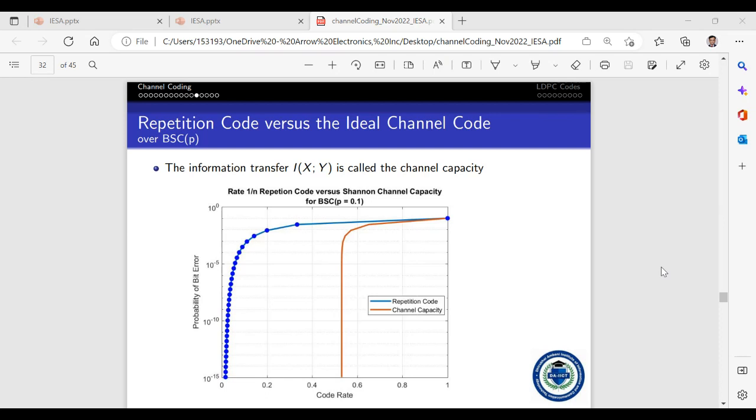Typically, in any communication system design, a threshold being accepted today, not as a formal requirement but as an informal guideline, is that if you're trying to do audio transfer like voice calls, you need at least 0.01, that is 1%, type of reliability, preferably 0.1%, 10 to the power minus 3.